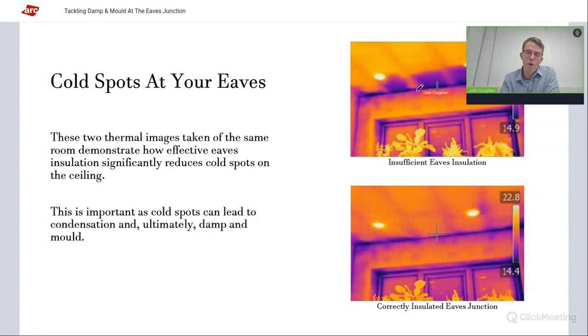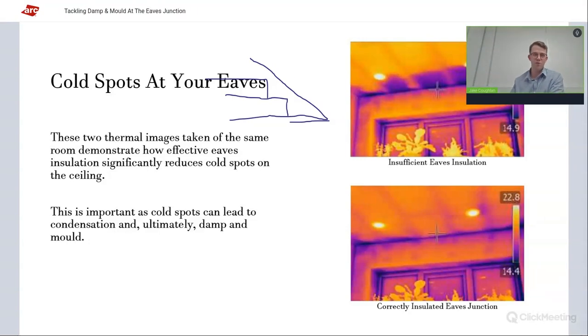That is fascinating. But this is a bungalow, and this is a bathroom, so they had a really low pitch. Surprisingly, this house maintained ventilation in the loft, and they had stepped insulation. It came up and across, and then another layer was up and across. So this is the area that has no insulation at all, and you can see it there. It's clear as day. This person, every year, was scrubbing this off using anti-mold paint, and every single winter it'd come back when it got cold enough outside again for mold to build up.